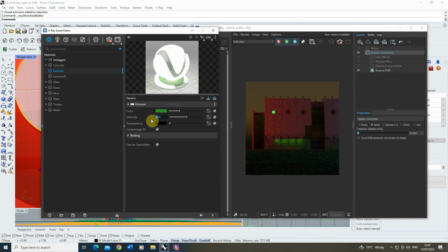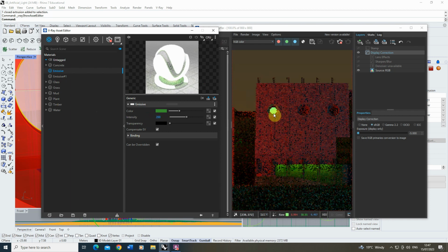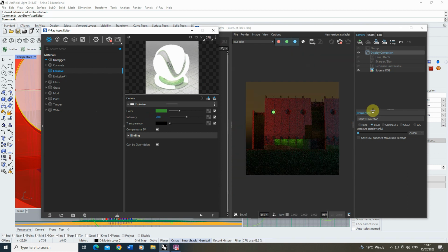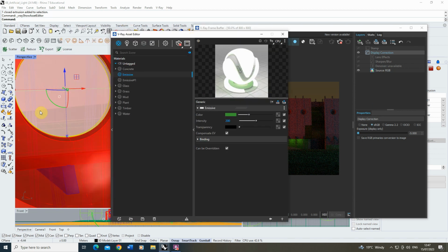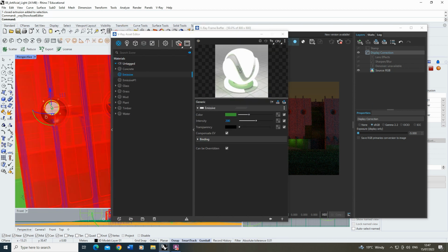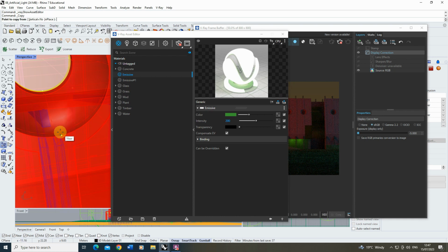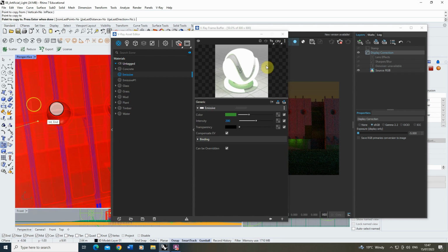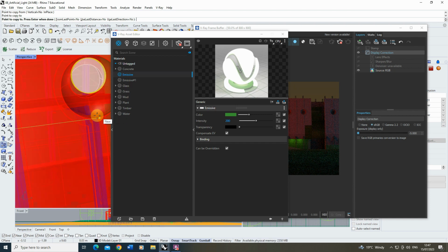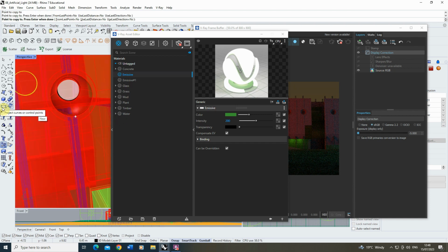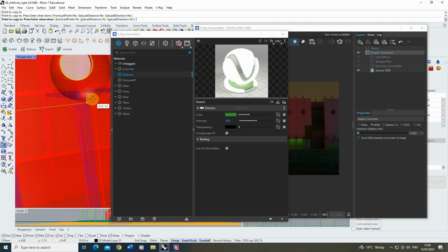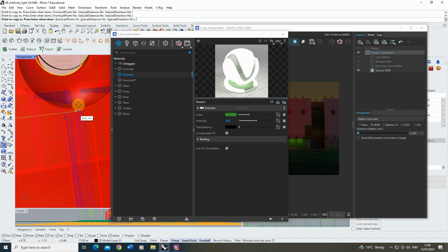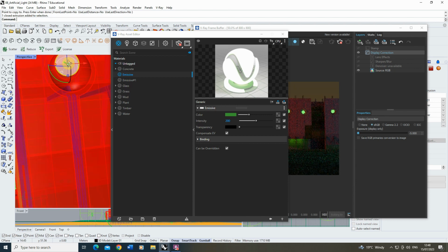And we're going to up that intensity slightly. Let's put it on a 200 to get a nice glowing effect. And then from there we could always copy it across as well if you want it in those other places. So we can start to create these little glowing eyes in the rest of the building. Let's copy this across to some of these in here. So these are all different ways of doing light materials, adding lights into your scenes and creating these different lighting effects.